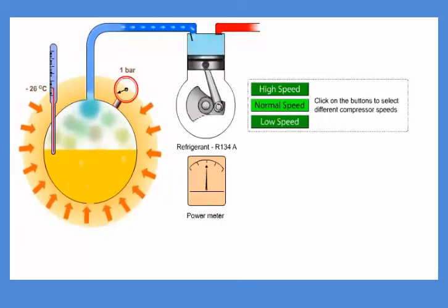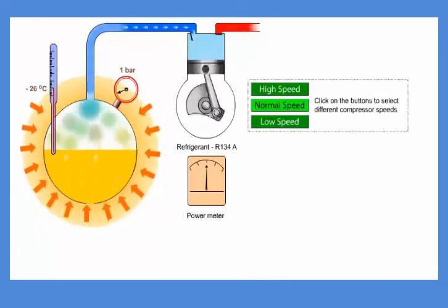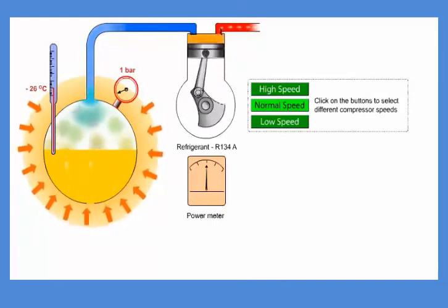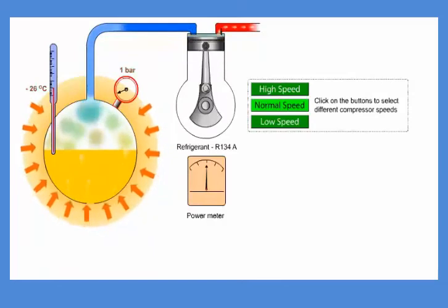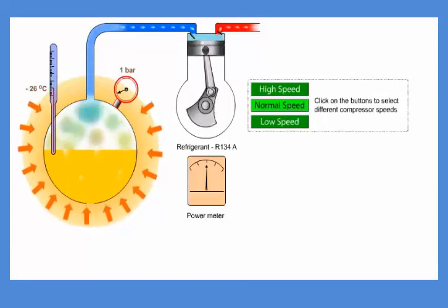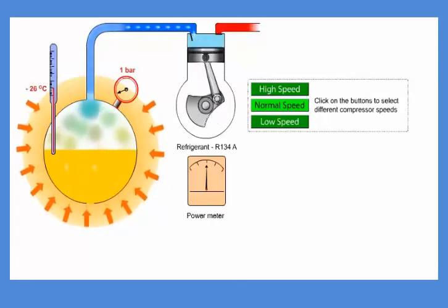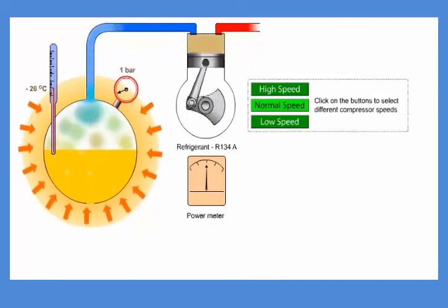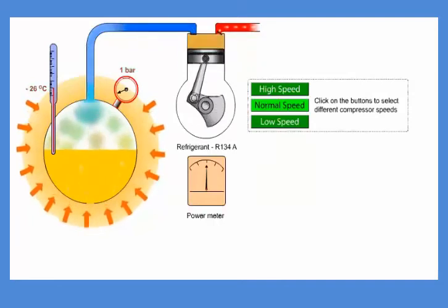There is coherence between pressure and temperature in the compressor, which leads to a higher temperature on the outlet of the compressor. The temperature on the compressor outlet measures plus 36 degrees Celsius in this case. In order to be able to compress the vapor, the compressor needs a supply of mechanical energy. In this case, an electronic motor is driving the compressor.